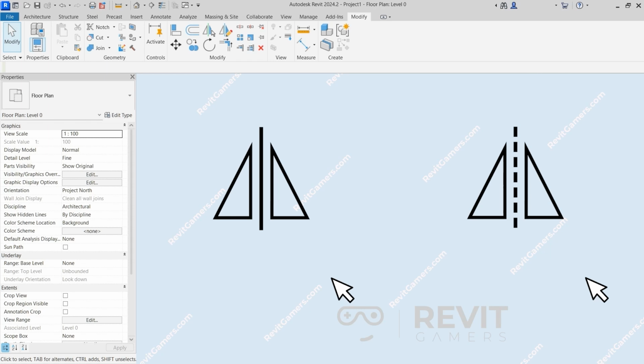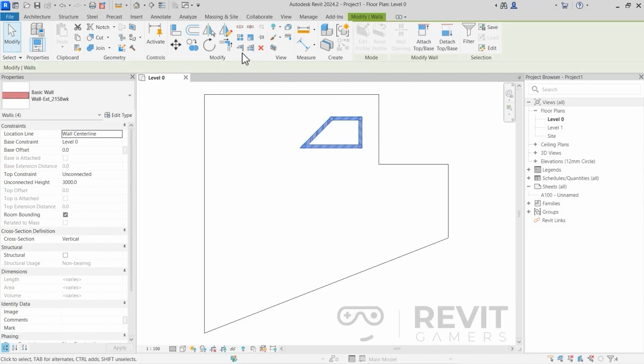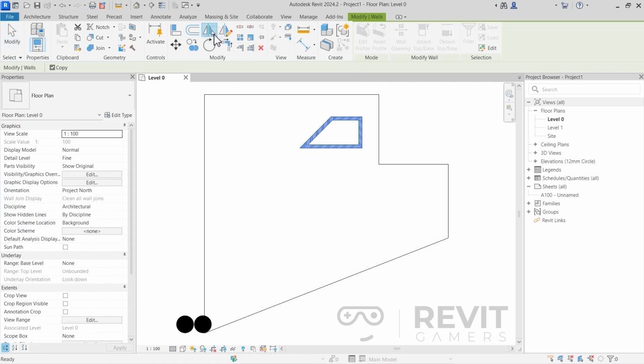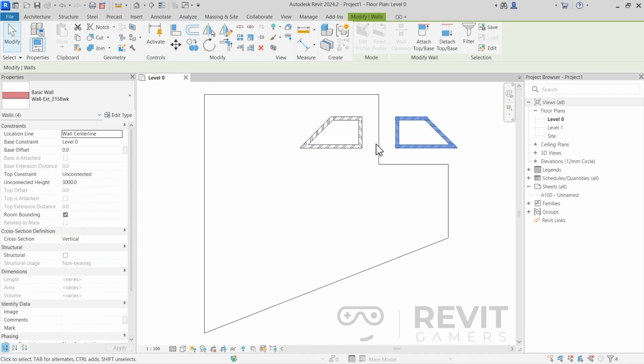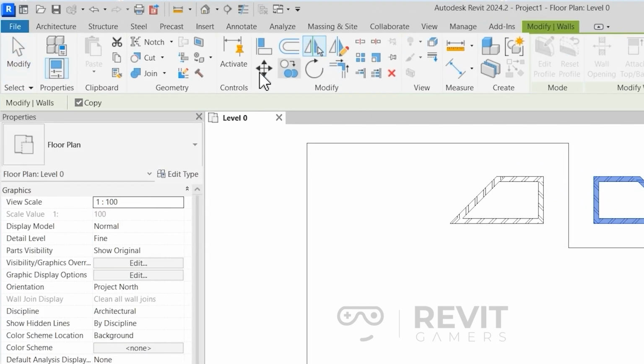Begin by choosing the object and then select the Mirror by Picking Axis tool or typing the shortcut keys MM. All required next is to select an existing line to establish the mirror axis. This line can be the side of a wall, the edge of a floor, the middle of a stair, or any other straight line. If you intend to mirror the object and not create a copy, ensure you uncheck the Copy option in the options bar.